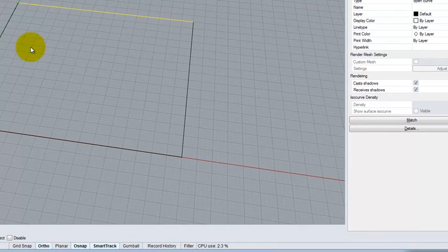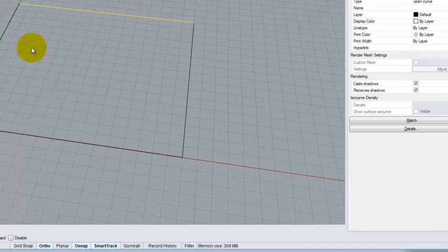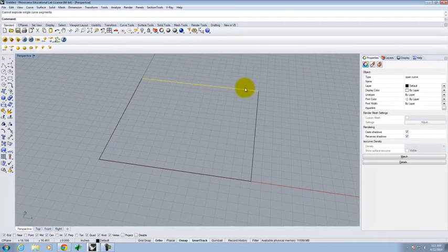Okay. Now, because we're going to start to get into a little bit finer detail and want to be able to control this pillow, it's very unlikely that a pillow is going to have perfectly straight edges on it. So we need to soften those edges and give them a little bit of curvature. And as we do something like that, we need to have some control points to be able to manipulate. We've already played around with edit points before. If I turn on my edit points, you see that I have a point at one end and a point at the other end.